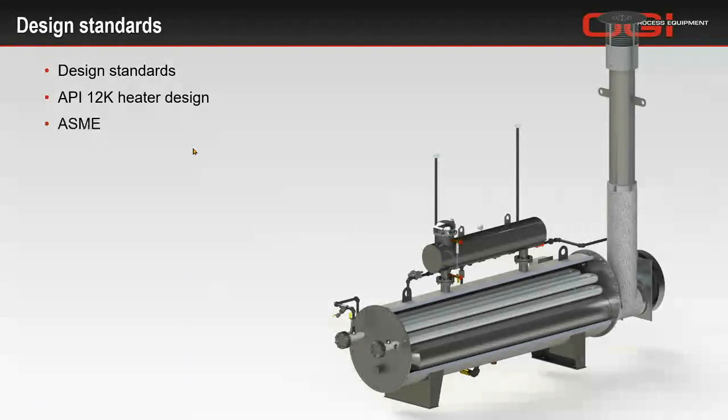We also follow ASME Section 8 Div 1, specifically for this process coil. This is a high pressure process coil. This is what makes your heater a pressure vessel and it should be National Board stamped with a U stamp.